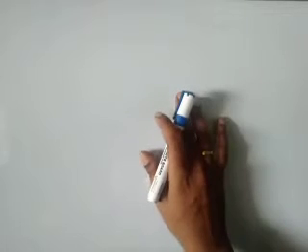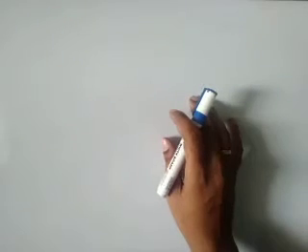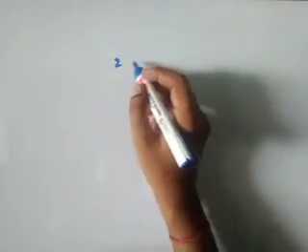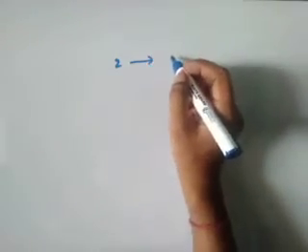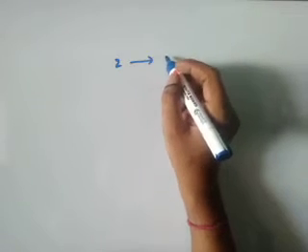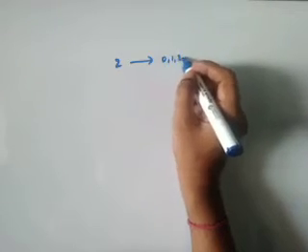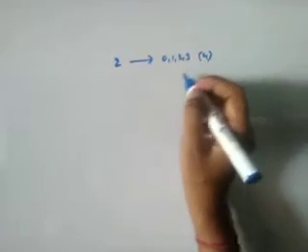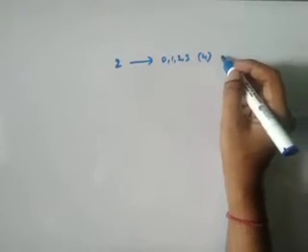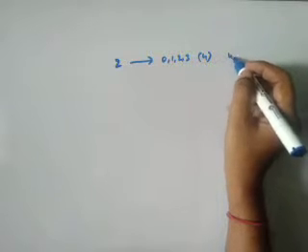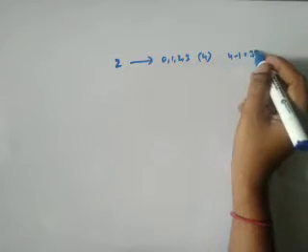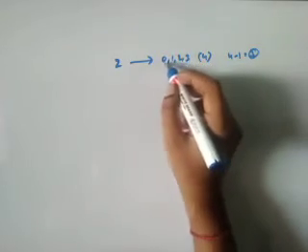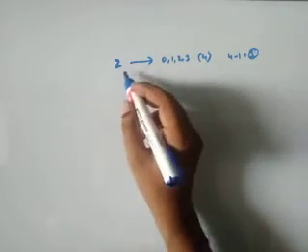We have also seen how it counts the numbers. If you have two flip-flops, how many events can be counted? It can count 0, 1, 2 and 3. So 4 events can be counted, and the last decimal number that can be counted is 4 minus 1, that is 3, but it can count 4 events. So that means we have taken a 2-bit counter.